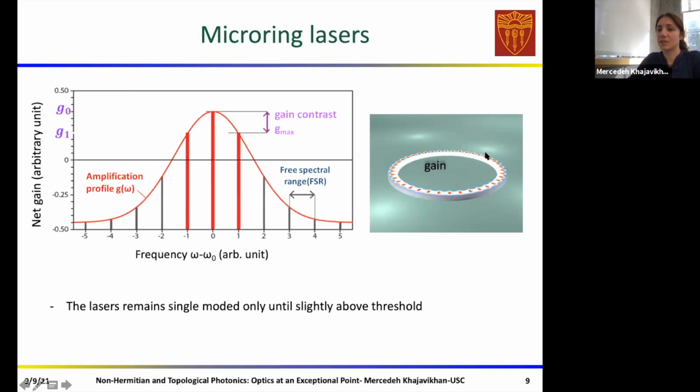Let's say we just get a ring resonator. A single ring resonator can actually support several longitudinal modes. So if this is made of a material that can provide gain, like most semiconductors, not most semiconductors, III-V semiconductors, you can see that there is an associated gain spectrum or line shape to this gain material. And if these are the longitudinal modes of the cavity, no, actually, realistically, most semiconductors have 50,